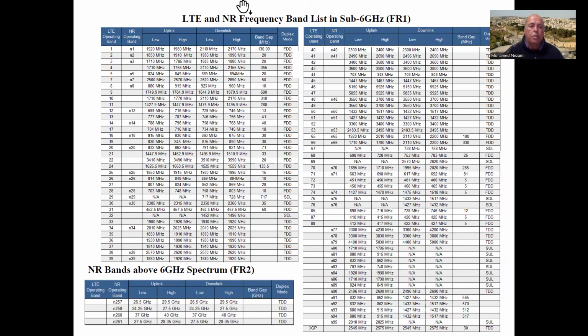For the rest of these here, most of them really, you could look at them and see that you can probably cover them with some of the devices that are readily available from Analog Devices and Texas Instruments or Xilinx, well, AMD nowadays, that utilize basically up to like 4 gigasamples per second. Very much you can subsample any of these frequencies.